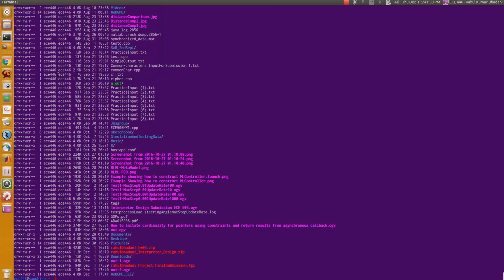In this video, I will show you how to use the ROS node modeling language created using WebGME to create a launch file that will be used to run a simulation using ROS and Gazebo. So let's get started. I will first unpack the npm package that will let me create WebGME apps and start the server.